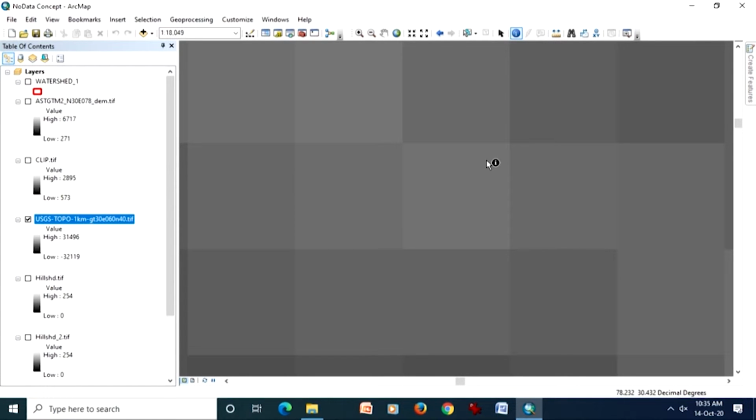Now, since we have digital elevation models available at 90 meter like SRTM, we can very well download for our area of interest, or 30 meter, or even nowadays you can get a 12 meter. For India, you can also get Cartosat based digital elevation model of even up to 5 meter resolution. But only a few tiles are available for India.